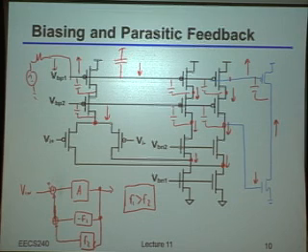Other tricks that people like to play, in the context of putting in a filter, is to, for example, put a resistor there, just to low pass whatever the positive feedback coming back is. But again, user beware, because you have to really carefully place that, A. And B, you also have to make sure that this local node here on that PMOS device doesn't get messed up from an impedance standpoint. Because as we'll talk about a little later on, adding a resistor into the bias like this of a PMOS transistor is a great way to create pole zero doublets. We'll actually intentionally do that later on down the road, but in other cases you may not want to do that.